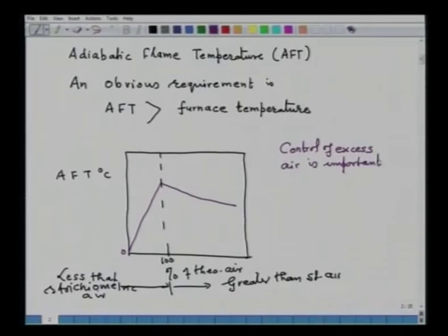Now, as I have pointed out in my lectures 9 to 12, which are on combustion and material balance, in reality complete combustion does not occur with the exact stoichiometric amount of air, because of certain practical difficulties which I mentioned earlier. If you have gaseous fuel, around 4 to 5% excess air is required.